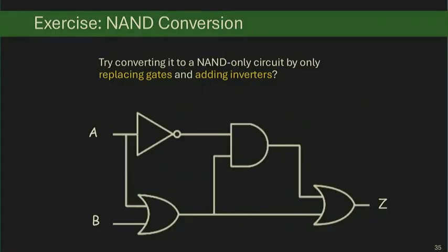All right. Here's, again, an exercise for you. Please try to convert this to use only NAND gates and see what you get. Again, this is not a very elegant 2-level circuit, right? It has like 3 levels, and they sort of go in this kind of fan out and then reconverging pattern. But again, try to apply this bubble pushing idea to convert this into a NAND-only circuit and see if it's feasible. Hint, it may not be feasible. Or not feasible without some additional transformations.